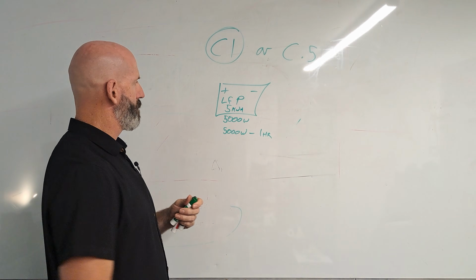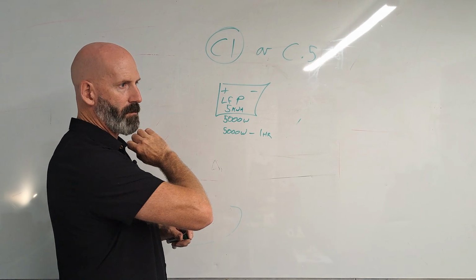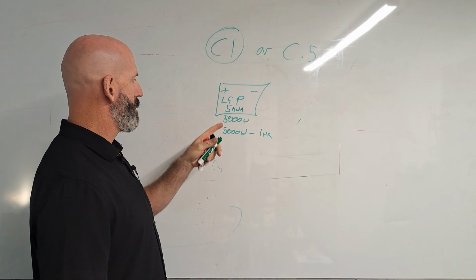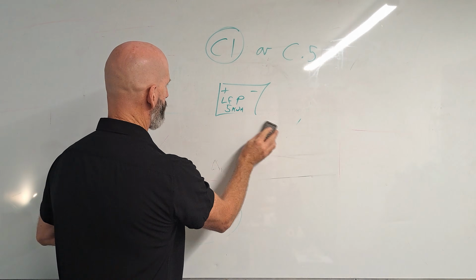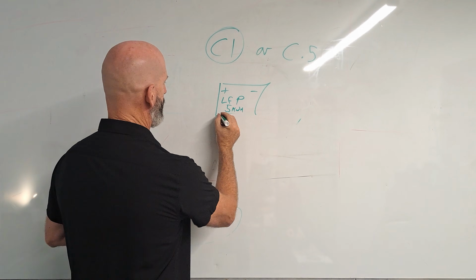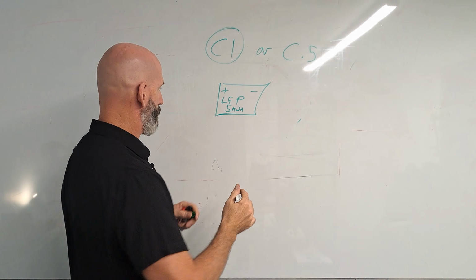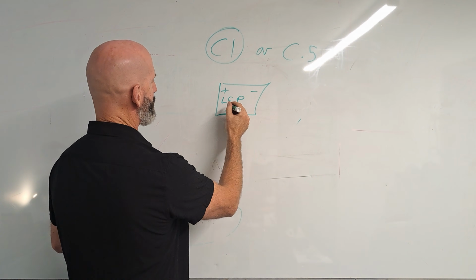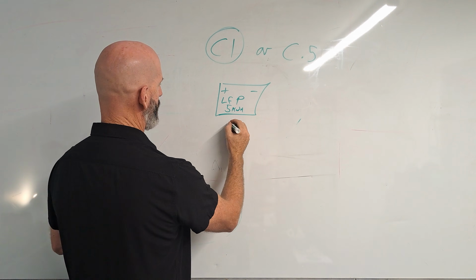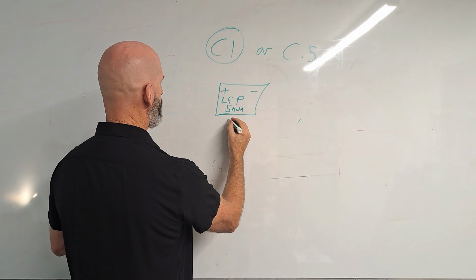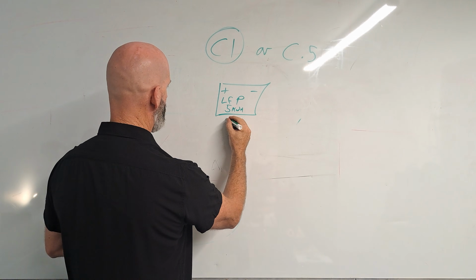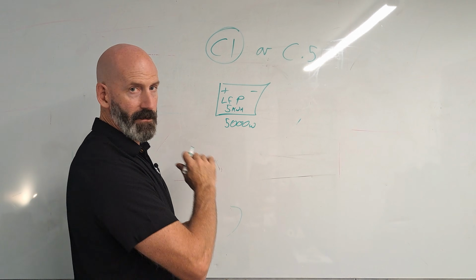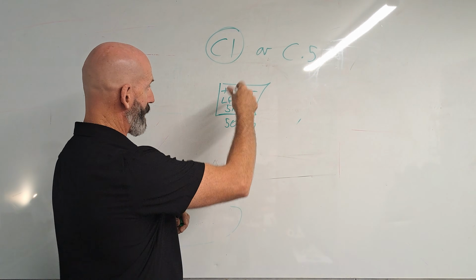You will find your batteries are listed in kilowatt hours. It's the volume of power, which is how much power it can deliver over a period of time. So 5,000 watts over an hour is 5 kilowatt hours. Now, what you've got to look at, your C rating, is your discharge rating. Why it's a C, I don't know. Anyway, well, I do, but we won't go into that. If it's a C1, it means it can deliver its entire capacity over the period of 1 hour. So a 5 kilowatt hour lithium battery can discharge 5,000 watts at any one time, and it can sustain that for a full hour and deplete the entire battery without doing any damage to the internal cells.